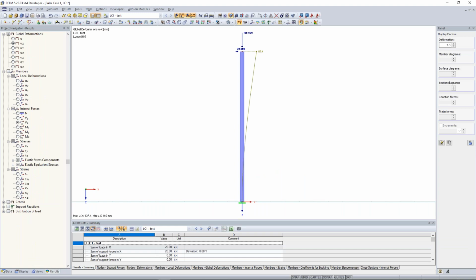First of all, we had the first order, the geometrical linear analysis. There we make the equilibrium of the whole structure at the undeformed system. And there the P delta method said to me that we make this equilibrium of the whole structure at an undeformed system. No, sorry, at a deformed system. The first order says we make the equilibrium of an undeformed system, and the second order, or the P delta, says to me that we make this calculation on a deformed system. Sorry for that.